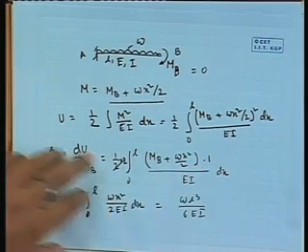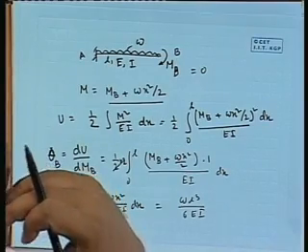So, it is just 1 unit, because if you take the derivative, it is P into something, so the P part will go away, and that will be defined in terms of 1 unit. From there we define it as the unit load method, because it is like putting a unit load there, okay. Unit load or unit moment. If we are interested in slope, we have to put 1 unit moment. If we are interested in deflection, we have to put 1 unit of force there, okay.